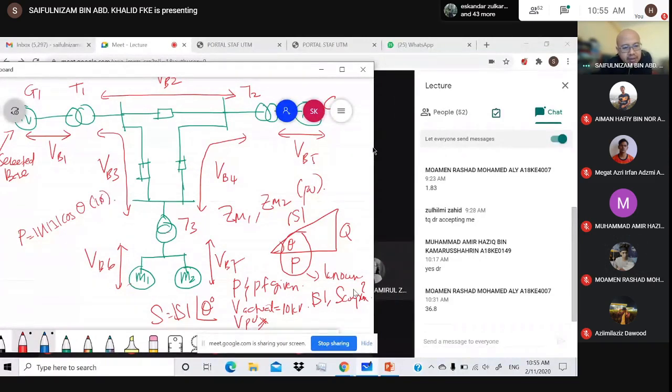So remember, for power, P one phase PU equal to P three phase PU, right? In per unit, power is the same. Then you can find the current from this relationship. You know the voltage, you know the power, you know the power factor, you can find the current. As I said, use your previous knowledge in analyzing the circuit. That one I cannot teach you based on your exercise, or your experience in your previous subject.